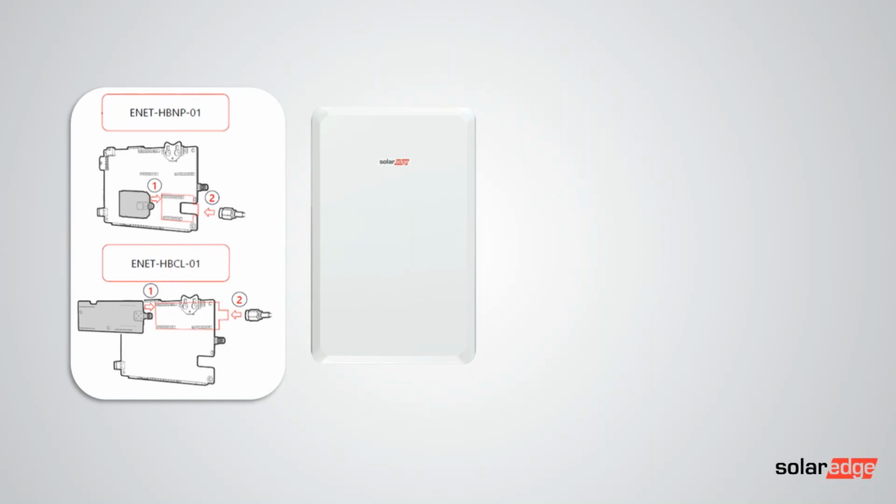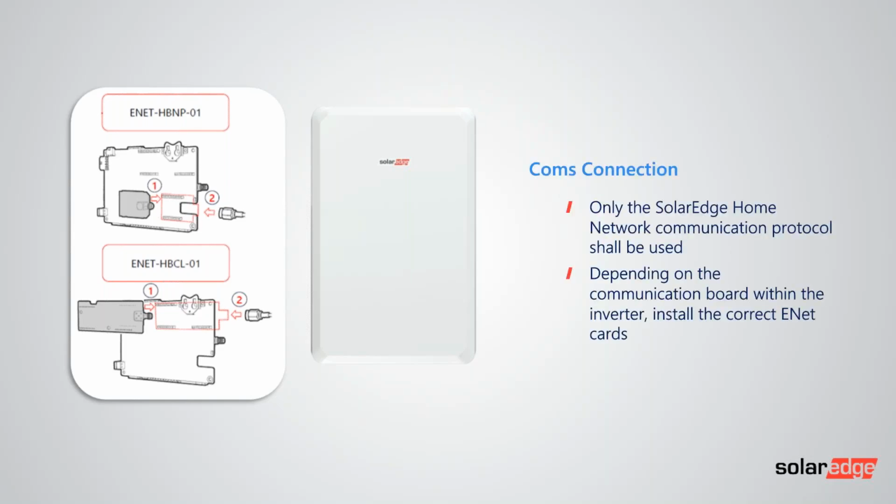Also, as Doug mentioned, EnergyNet is the mandatory communication protocol. What is really important is to understand the fact that the residential three-phase inverters may have two different communication cards in them. So one basically has a single comms board slot on it and the other one has two. Because of that, there are two different EnergyNet cards. As you can see there, one is the EnergyNet or ENET HBNP-01 and the other is the HBCL-01. The simple way to approach this is if the card in the inverter can take the small EnergyNet card, use that one. If it can only take the big one, use that one.